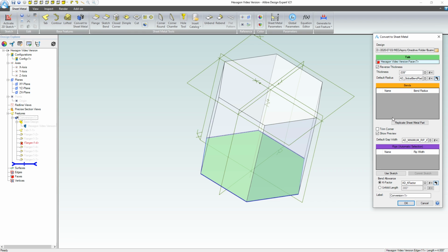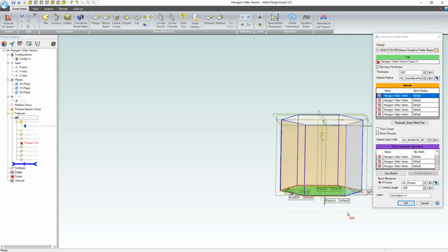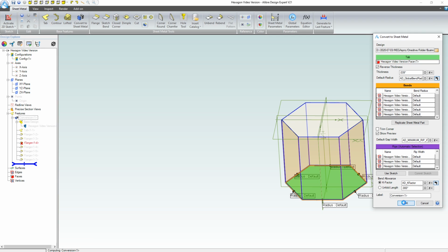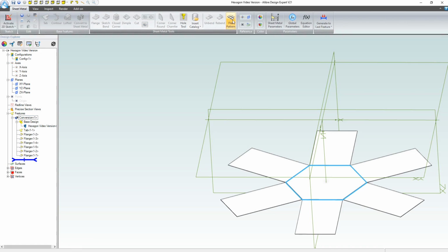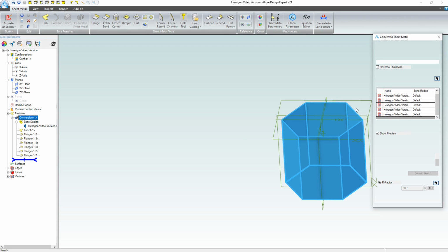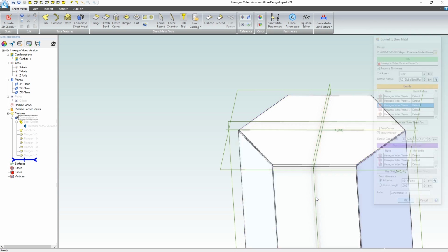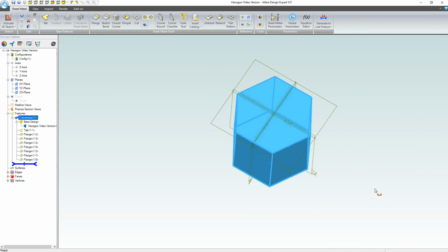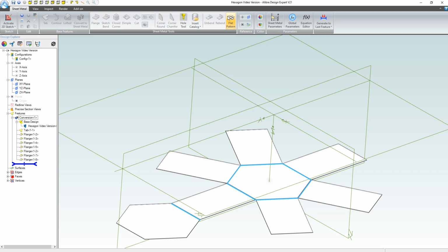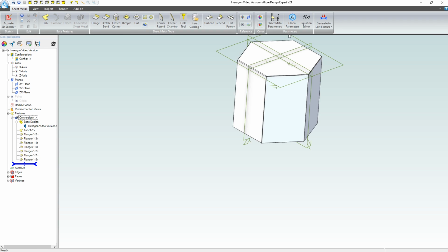Perhaps I can redefine also a new way of bending this out. Right, so I can define bends at every part of the base, and when I flatten that out, we have a radically different flat pattern. Let me go in and also, this time not in a way to promote an error, define a bend here. And now I have a hollow figure with a top on it. And I can extract a flat pattern and see exactly the sequence that I would need to create this.